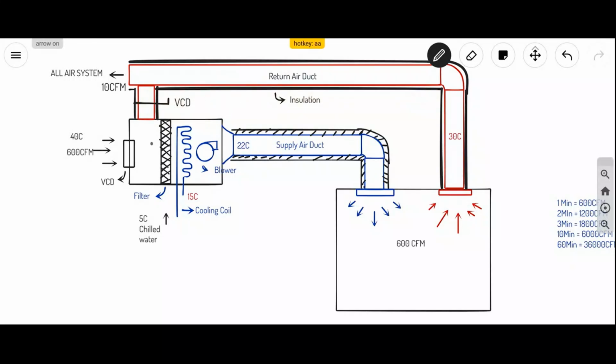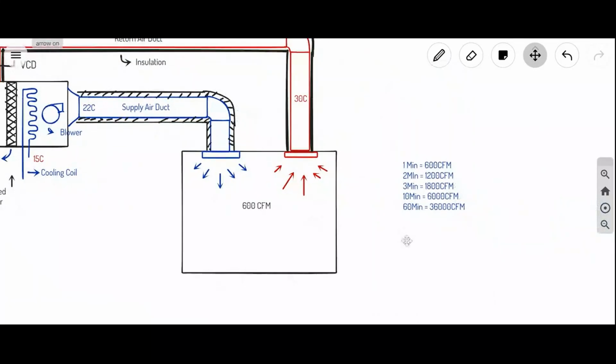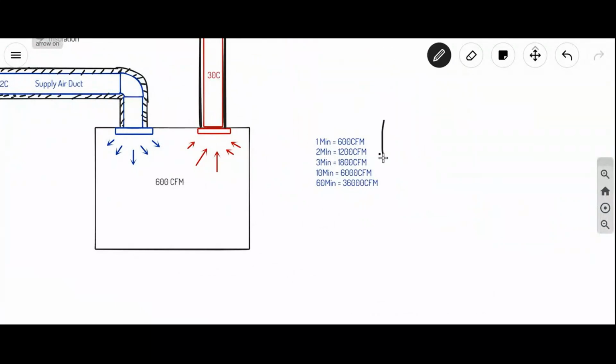And I am taking 590 CFM from here. I am adding 10 CFM of fresh air from here. Right? Every cycle I am doing this. Okay, in every cycle if I am doing this, will it balance my fresh air oxygen level? So it is going to balance the oxygen level. So here, how the 10 CFM is defined, we'll see here.